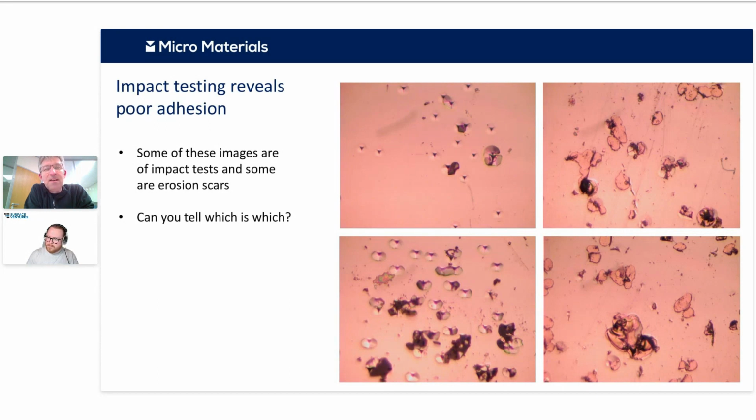We have the velocity in and the velocity out coming directly from the curves. So with the mass, we can determine the kinetic energy in and the kinetic energy out, and from that we can say the kinetic energy loss. People have also done potential energy and things like that. I didn't in this, but certainly Janet and co-workers at MPL have done it that way as well. So there are quite a lot of different options, but the kinetic energy absorption or kinetic energy loss works quite nicely. But you do need to calibrate it for the mass.